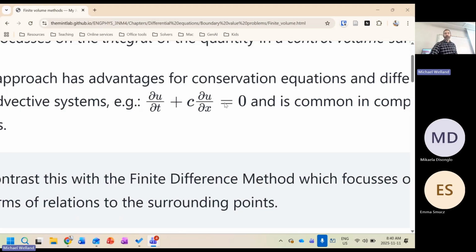Okay, so this is the quintessential convective equation. You have some quantity and the rate of change is equal to the velocity or your movement, right? C times some gradient. Okay, which is different from this guy. This guy is the second derivative. This one is only the first derivative. Does that make sense, that difference? Typically, they appear together. You almost always have some kind of diffusion, but in most cases, frankly, you would have something like this. If this term gets too large, it's going to dominate this guy and you're going to have numerical problems.